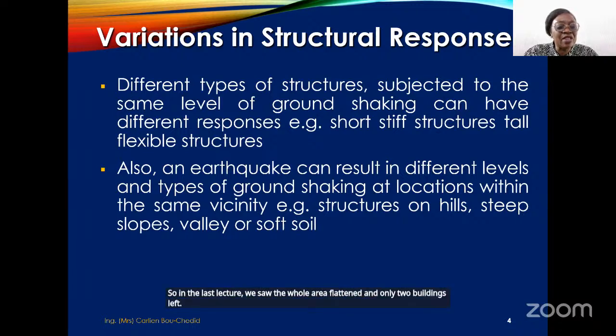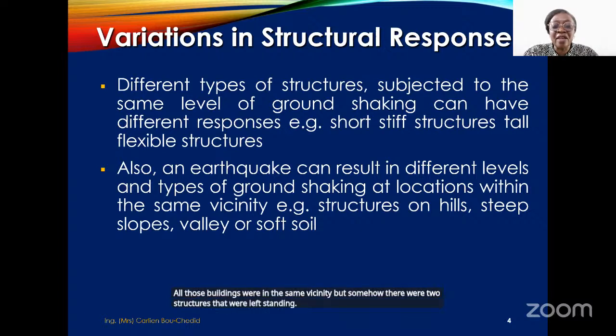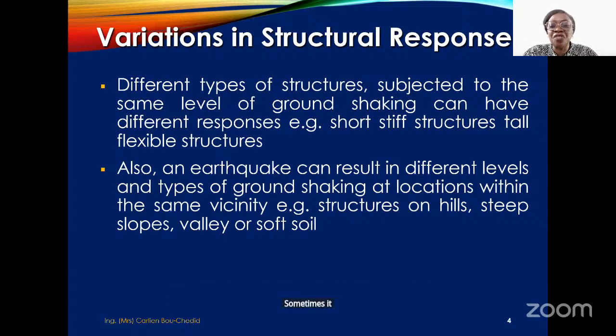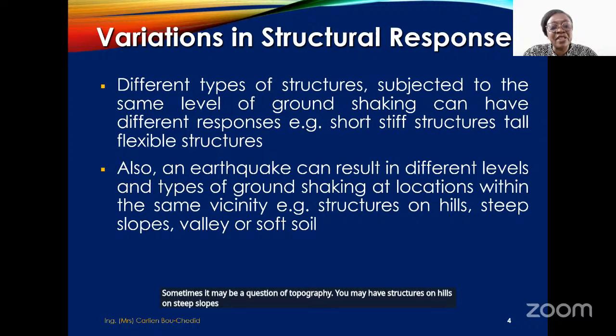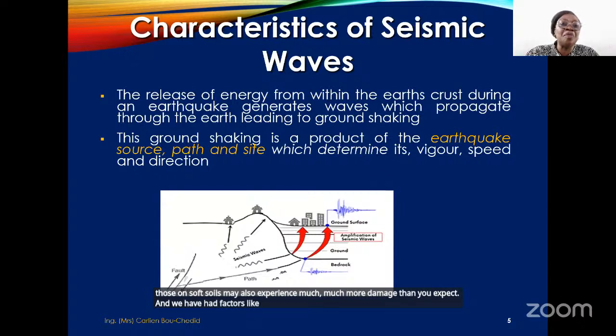All those buildings were in the same vicinity, but somehow there were 2 structures that were left standing. Sometimes it may be a question of topography. You may have structures on hills, on steep slopes, experiencing greater damage than those perhaps in a valley. Those on soft soils may also experience much more damage than you expect. And we have had factors like resonance mentioned.